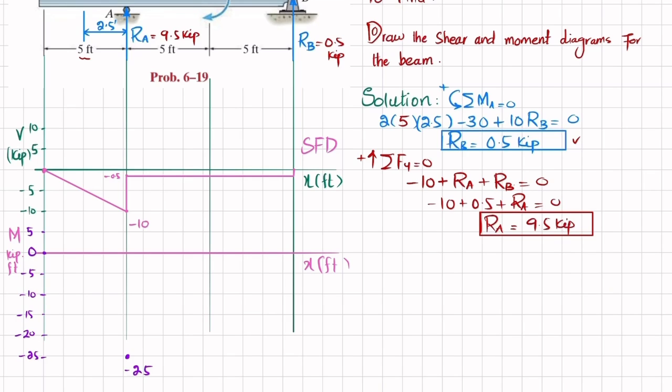So you can see that shear force is a linear line, a first degree line, and its slope is decreasing. So bending moment will be one degree higher, which means it is a second degree line, and the slope will be decreasing, in a clockwise direction. So it will be like this. So let me join this in curve form. It will be like this.